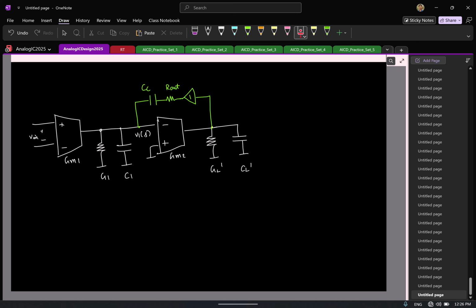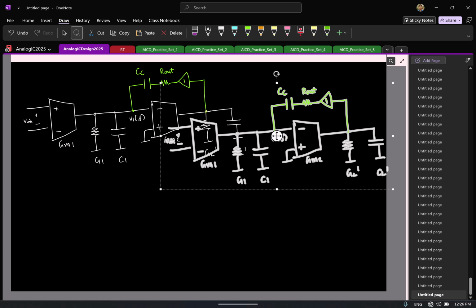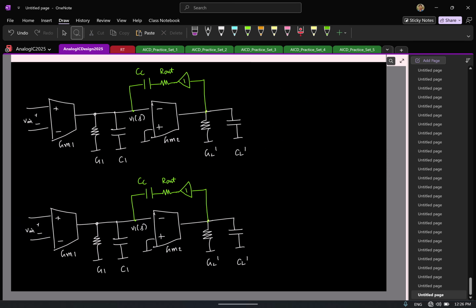Now, what we have done is basically added a buffer in this part so that we can kill the feed forward conduction. So just like how I can add a voltage buffer, what can I add? Okay, I thought I was leading you to the correct thing. Just like you have a voltage buffer, what buffer can I add? You can also try to add a current buffer actually. So even if you put a current buffer here, again same thing, right? Current can only flow this way, not the opposite side. And how do you make a current buffer? Simplest current buffer, common gate. So you can try to do that.